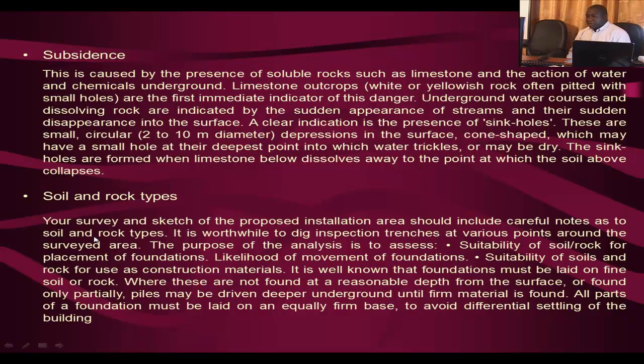Now we talk about the rock and soil types. During your survey, you need to sketch the proposed installation area and make careful notes of the rock and soil types. It is worthwhile to dig inspection chambers and trenches at various points around the survey area.